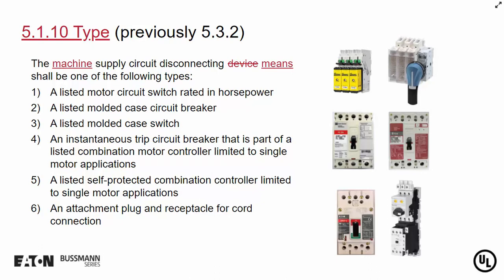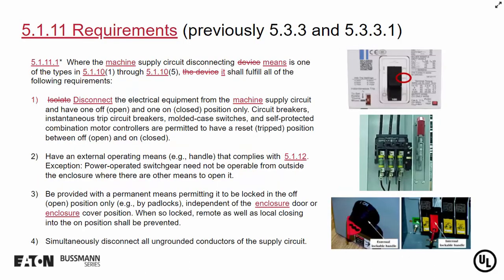So again, you have a very simple machine here. And of course, the last requirement, the last permitted main disconnect type, is an attachment plug and receptacle for cord connected equipment.